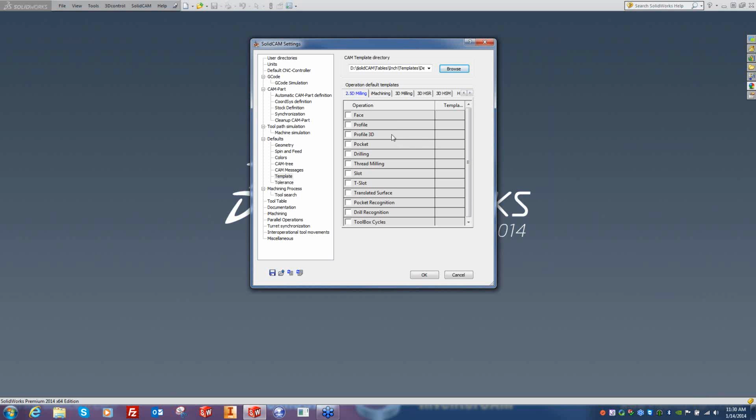But you can start off with a particular template for any given toolpath, like face mill. You could have 5 different templates that you prefer to use. And you can create those. So every time you start a face mill, you can always have your depth set, or you can always have a tool picked, or whatever you want as a default in there, you can create in templates. In order to do that, that happens inside the actual toolpath itself.